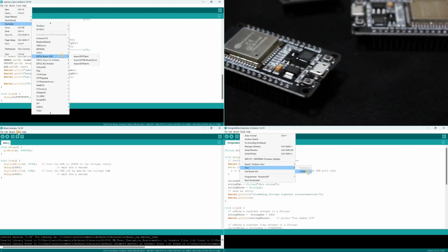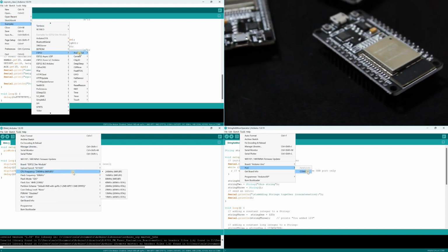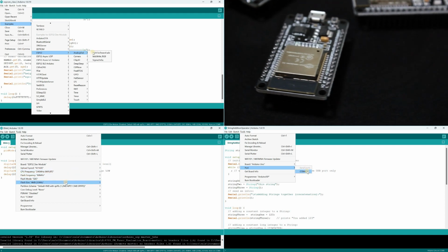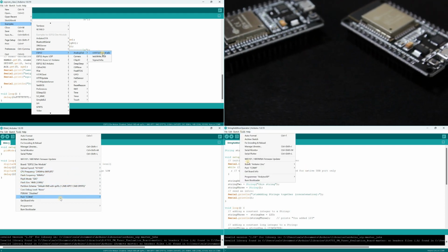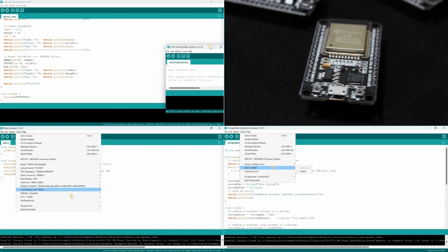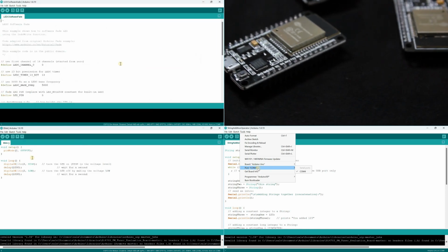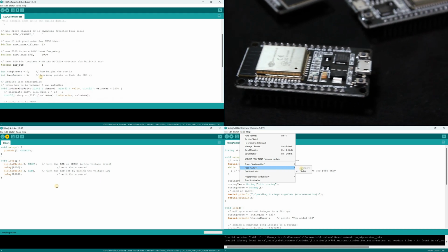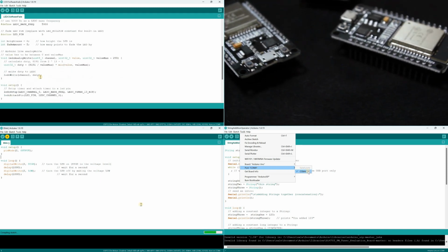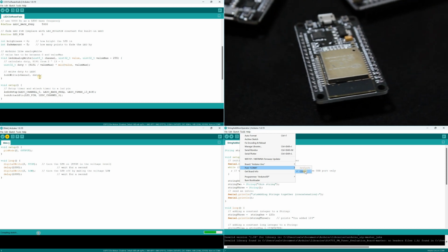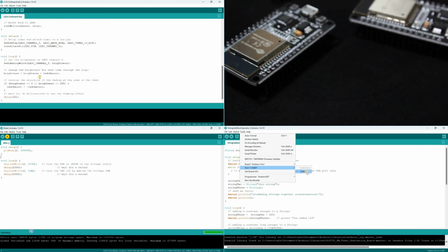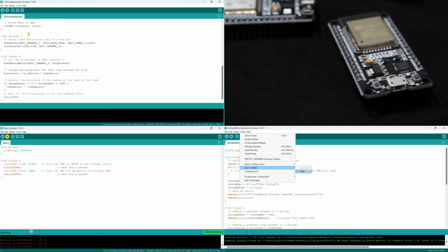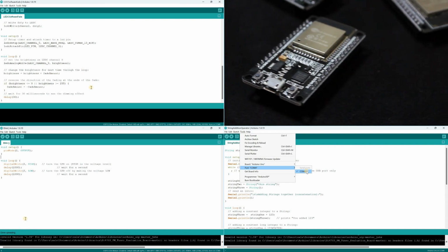We have also covered the process of connecting the ESP32 to your computer, selecting the correct board and port, and uploading the code to the board. We walked through the blink example and verifying the blinking LED. Furthermore, we delved into configuring the board, exploring additional examples and functionalities, and showcased the simplicity of programming the ESP32 Devkit using the Arduino IDE.